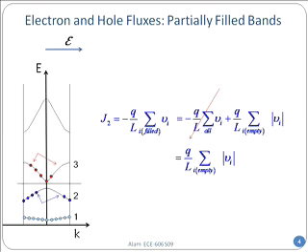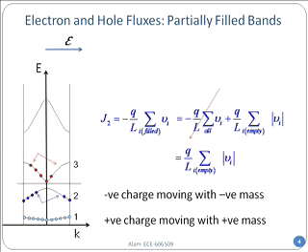And you can see the direction the electron goes is the same direction the white space goes, because white space cannot move by itself. It's moving because the electrons, or the black cars, are moving. So that conceptual framework gives you the idea of why the charge is positive and why they move in the same direction as the electrons do. The empty states move in the same direction as the electrons do. Now, this is a very important concept, and I hope you'll spend some time thinking about it clearly.